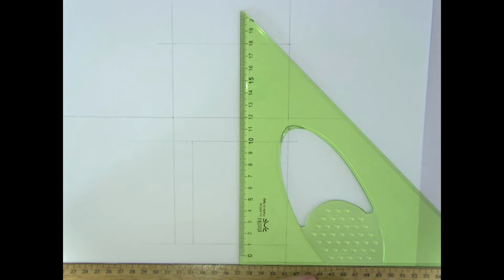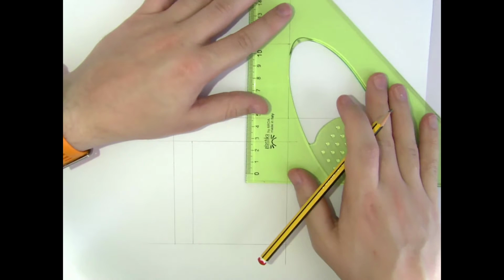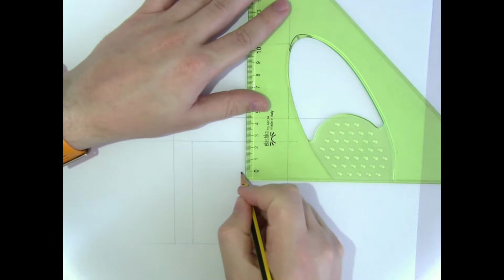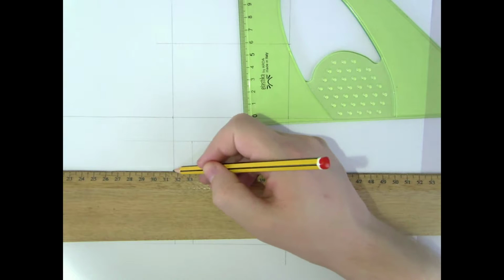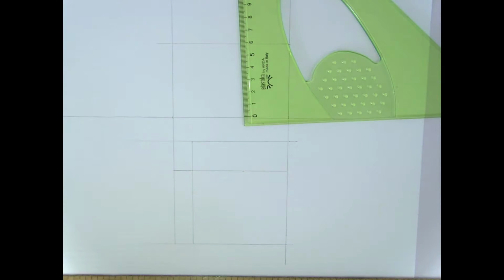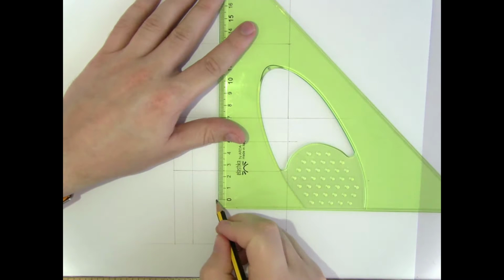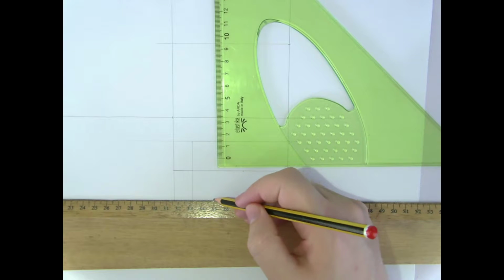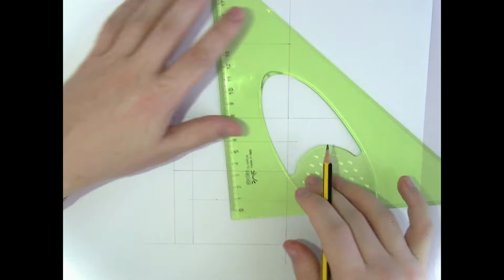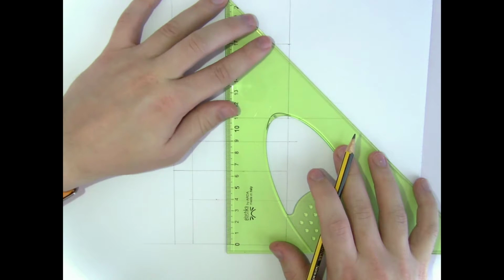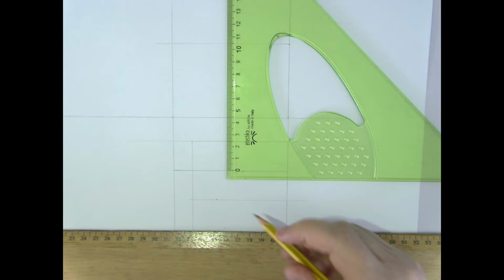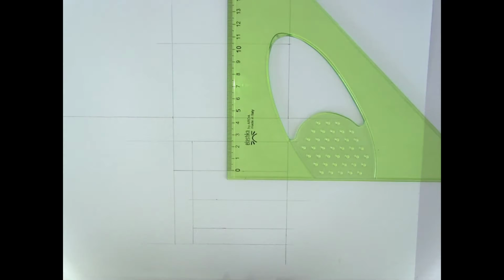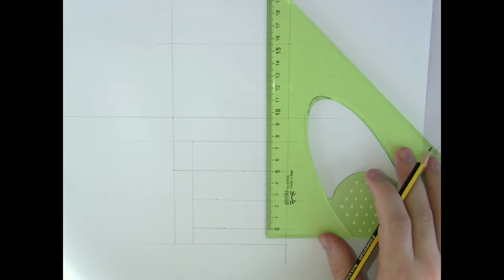After that, then we have a number of steps. The top one is out 25 millimeters. As we can see, it's in line with the flat piece of the wall. So this is 25 millimeters, and it's our top step. Underneath that, the second step out is also 25. So drawing all this in lightly, and then the bottom step is back 15 millimeters from the front, which is here. Which also ends up being 25.